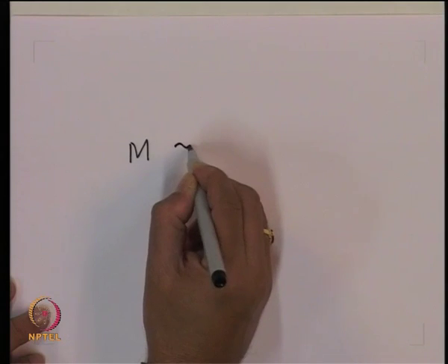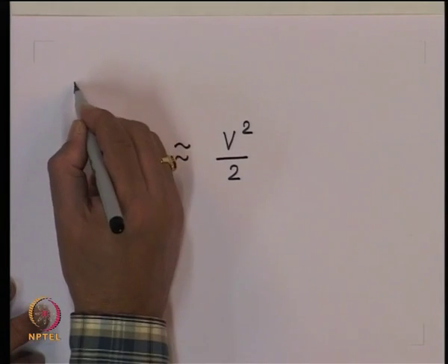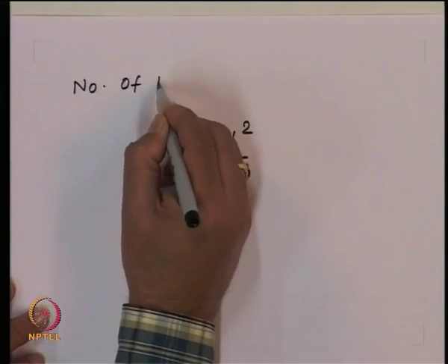Like that, if we consider the degeneracy for all the modes which are going to propagate for a large number, one can then sum up the total number of modes which are going to be present in each of these groups, and then one gets a result which gives us the total number of modes which are going to propagate inside the optical fiber, and that is approximately given by V square by 2. So, the total number of modes M is approximately equal to V square by 2. This is the number of modes.